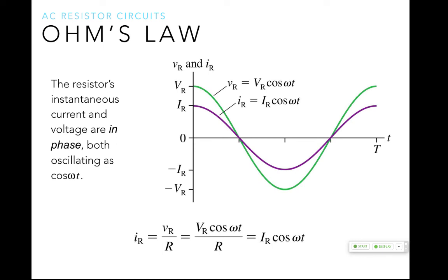That is a joke. Okay, so if you want to figure out your instantaneous current, you get your maximum current, that's from V equals IR. Okay, that's your current for your peak, right? And then this is your maximum current cosine omega t. Okay, and you'll notice current switches direction every half cycle because you're oscillating back and forth.